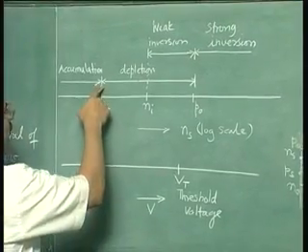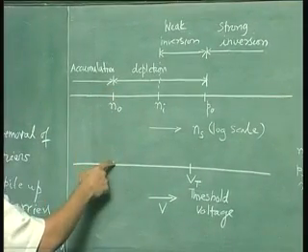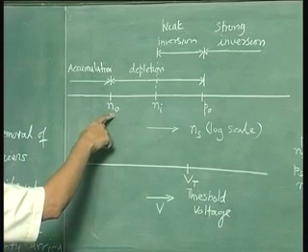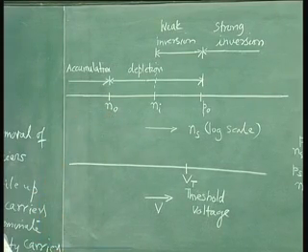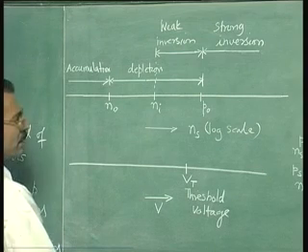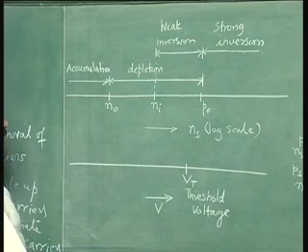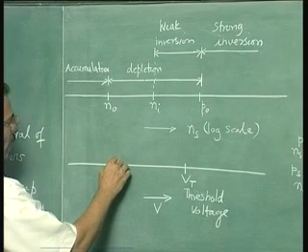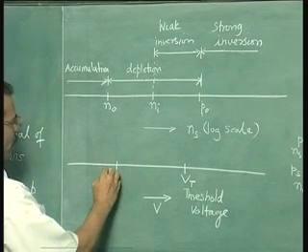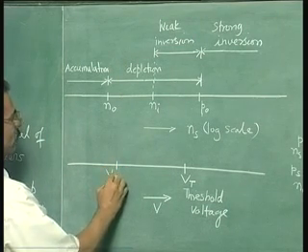On the other hand, this point where the surface concentration of electrons is the same as the bulk concentration, or when the charge conditions in the device are 0, is normally referred to as the flat band voltage.